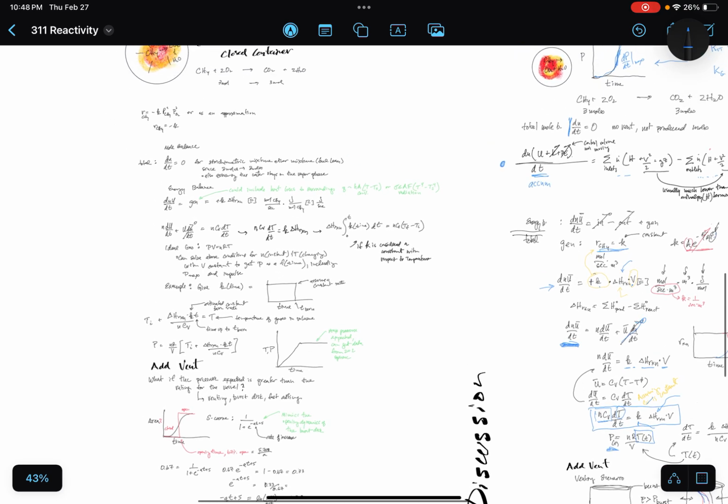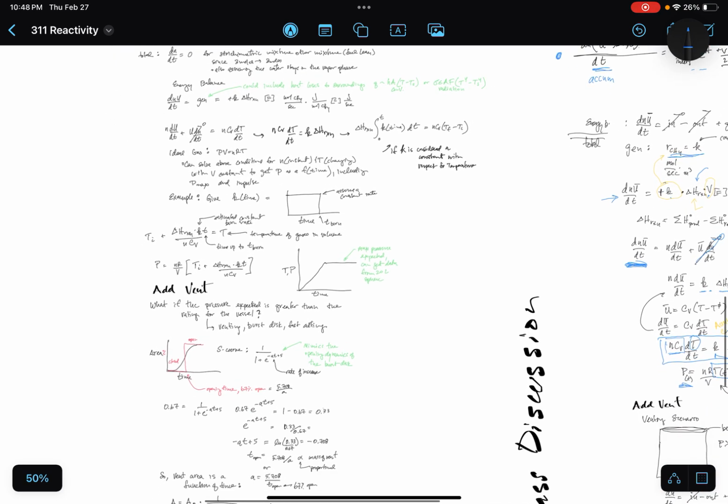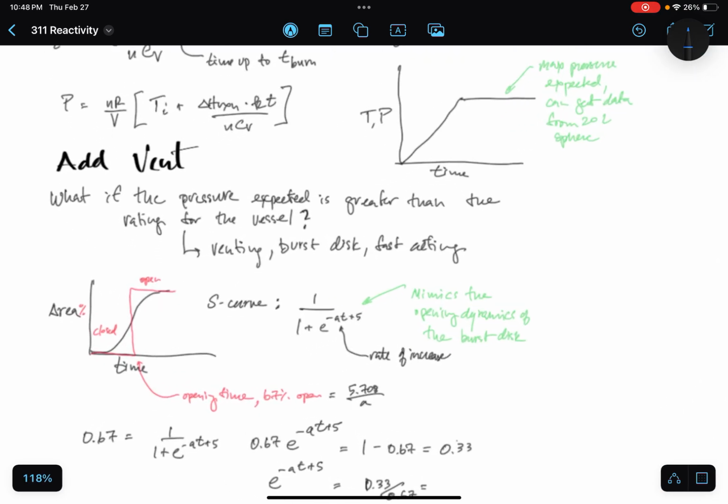Over here is some more details. I went a little more into how the vent actually moves out of the way. It's not just instantaneously that you get an opening vent, but typically you move from closed to open. And you can use physics where pressure pushes on the panel and opens it, and you can calculate accelerations and velocities of the panel, or you can just estimate it with an S-curve kind of a thing where that vent opens gradually.